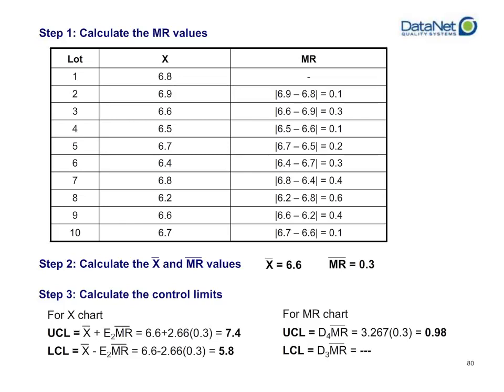Therefore, you need to make sure that when you do your average calculation, it is by the number of points for which you actually can calculate a moving range. In this case, you can calculate 9 moving ranges, so your average is going to be out of 9. Your average is not going to be out of 10. So take care. That first MR value is not 0. Your X bar, on the other hand, is absolutely out of all 10 points. You're going to want to make sure to include all 10 lot values for your X bar and divide by 10 in this case.